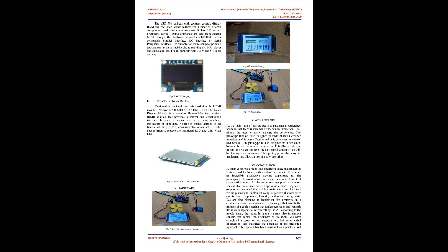The module can also support up to 2 stepper motors. Each stepper motor takes the place of 2 of the DC motors, so you can run 2 stepper motors or 1 stepper motor and 2 DC motors or 4 DC motors.